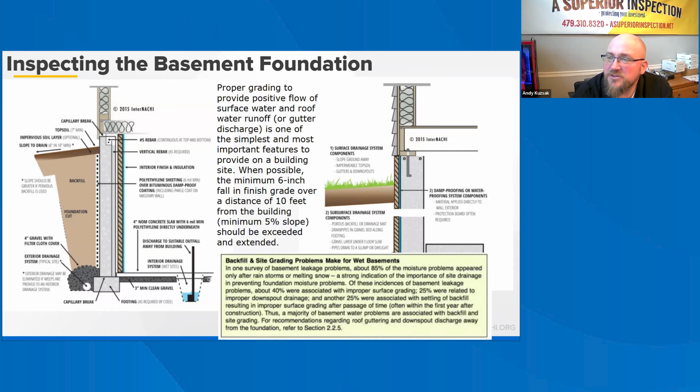A site-specific soil investigation or extensive local experience confirming consistently deep groundwater levels is needed before assuming soils are well draining. Where the foundation drainage system cannot be drained to daylight by gravity, a sump and pump must collect the water and discharge it to a suitable outfall, a safe distance from the building foundation.